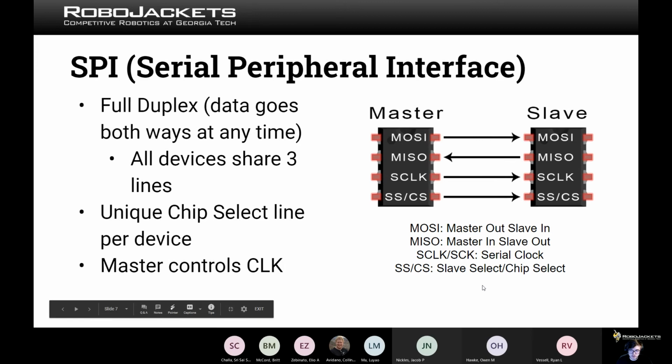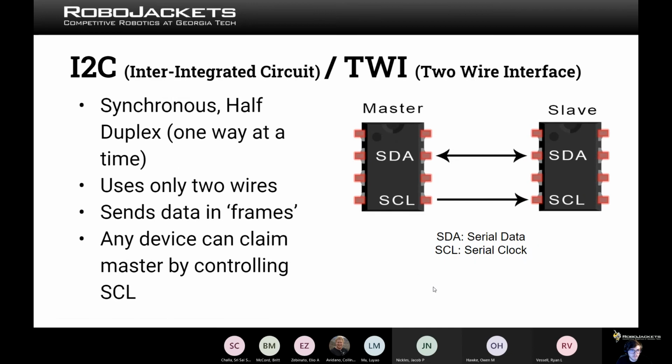Of course, when you have multiple devices on the same bus, that will reduce your effective communication time between master and slave, because it's one at a time, because multiple will be trying to do the same operations on the same bus. But if you only have one SPI port, then having multiple slaves on that with appropriate number of chip selects is a convenient way to do it, we'll say.